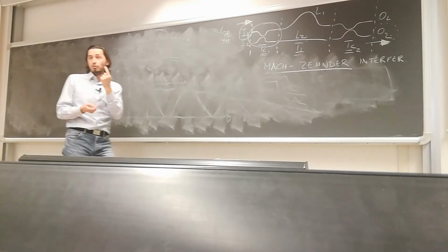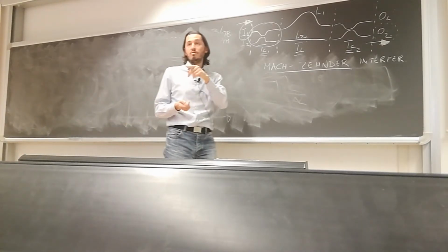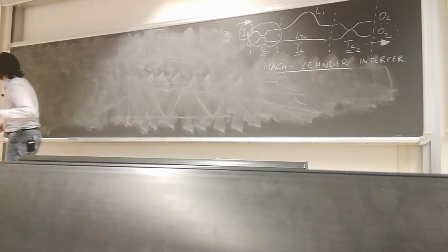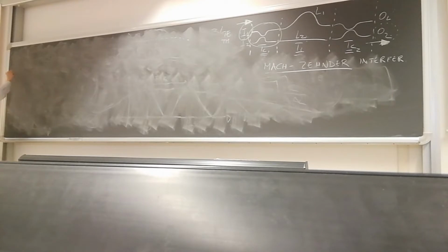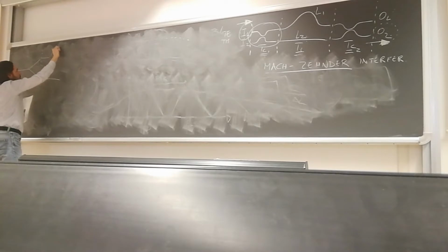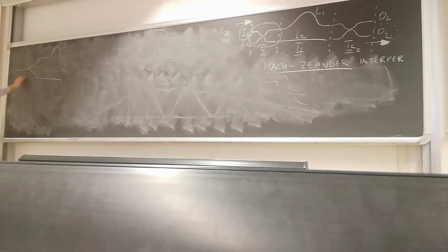So we didn't use the second input port of the interferometer. This means that in practice, what you could use instead of a directional coupler is a 1x2 Y branch. Do the same, just replacing the 2x2 directional coupler with a 1x2 Y branch.